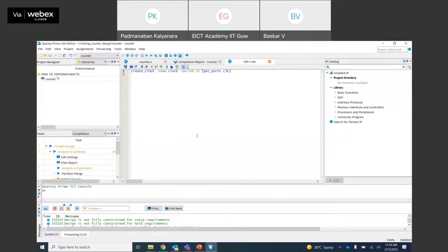And it starts from the clock pin of the register and ends at the data pin of the flip-flop. It starts from the clock pin and ends at the output port. But now, the kind of path we are discussing is a design with a pure combinational logic path, where it does not have any flip-flops in between. If that is the case, how are we going to constrain a pure combinational logic path? That's what we are going to understand.